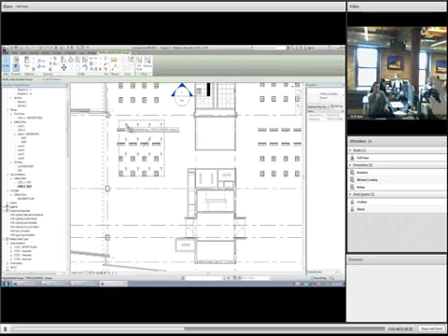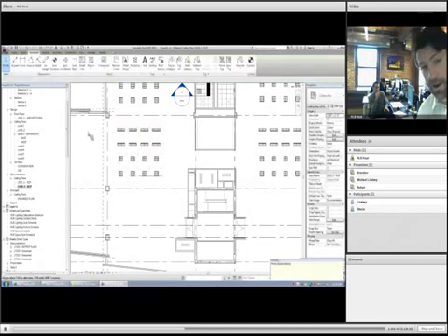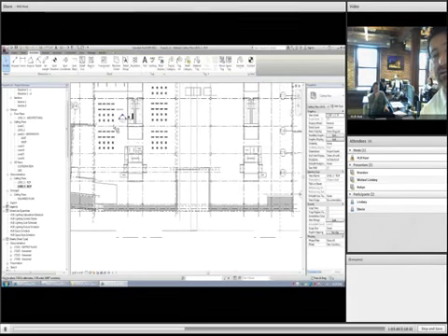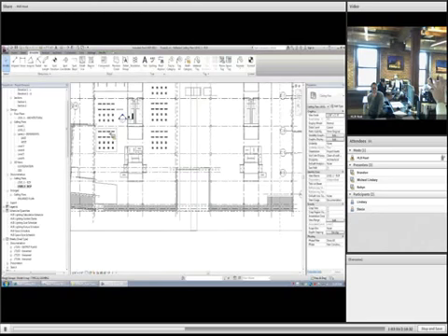Some people said, oh, if I have other fixtures in that plan, it's not working. Now, the way of really handling that, I think, is the easier one. You just say, okay, maybe you have to do it in certain places. You can't do the select all instances at one time. Maybe you select all tags in the one area that you need to move, and you move those independently. There's a variety of ways. I think that's an internal question if you really do want to pursue.